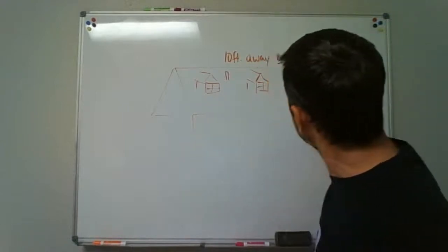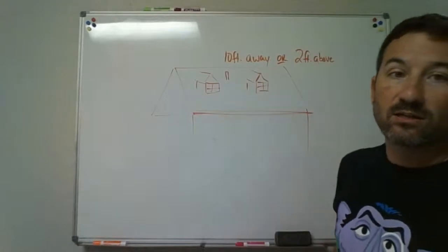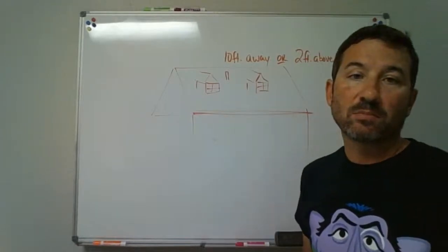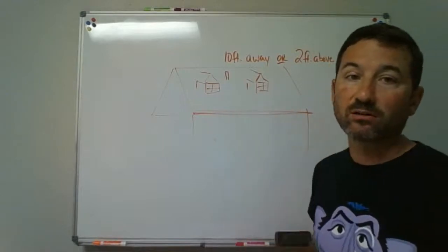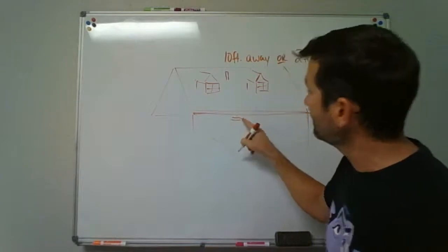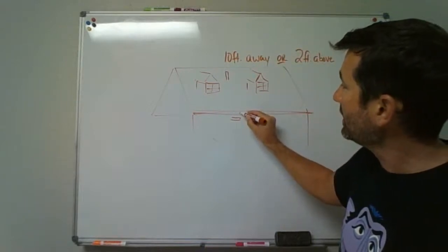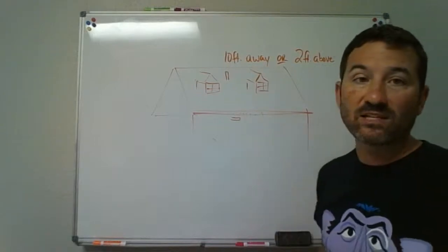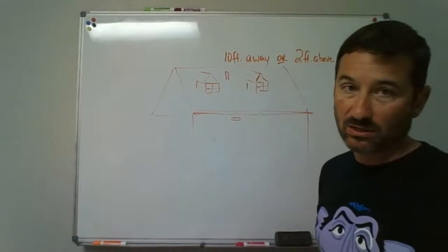Maybe you've got something that's coming out, and underneath this overhang there's going to be a lip. If you look up under there, it might have little holes under that soffit material. So if you had a vent coming out the side of the house, you wouldn't want to vent that underneath this overhang if it had little slots in there, a ventilated soffit. That sewer gas could come out and go right up into the attic space.